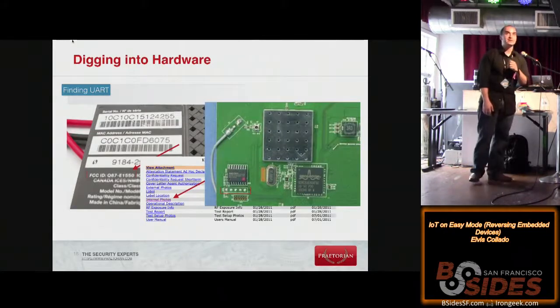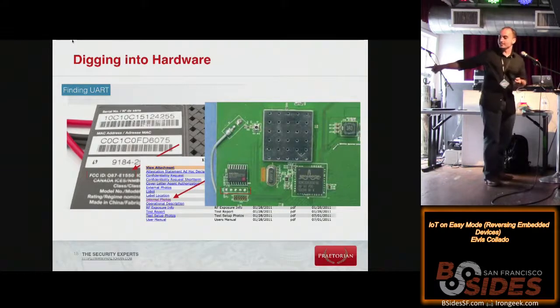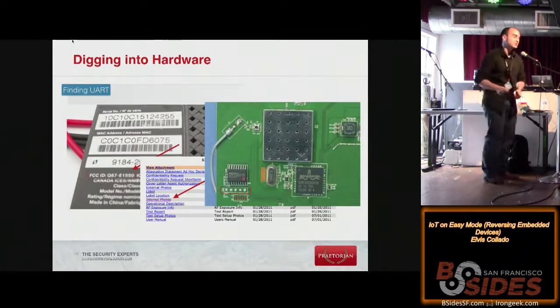I start seeing kind of like a pattern. A lot of people in here who have ever done this kind of stuff before recognize that pattern. Those 5 pins right there that are not soldered. It looks like UART. It looks like a serial interface. So let's try it out.